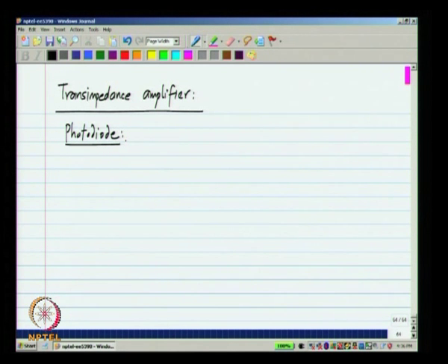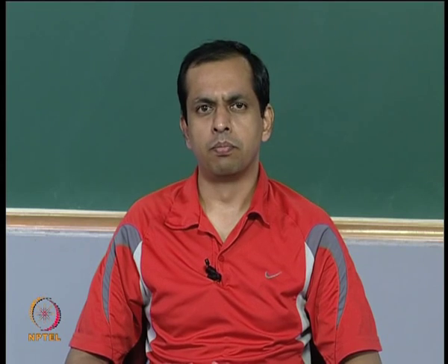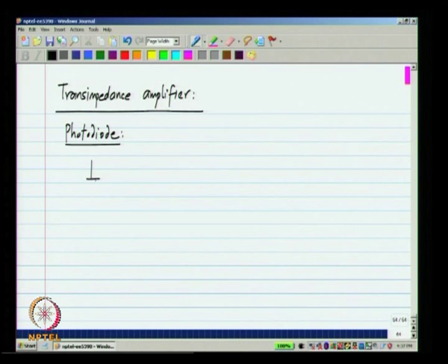As you probably know, a photodiode responds to light shining on it by producing a current. Usually you have a reverse bias diode, and when light shines on it, some current tends to flow through the diode. Normally, a reverse bias diode carries no current, but in a photodiode, when light falls on it, there will be a current. This is represented by a current source.